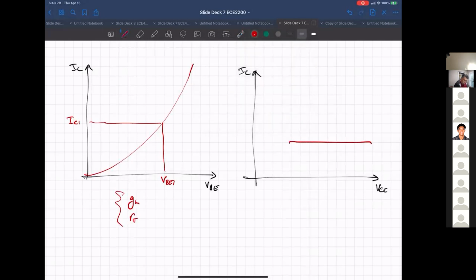you basically just want to calculate VCE to make sure you're not in this bad place. A lot of times when you design a circuit and it doesn't work the way you expect, you've screwed something up and VCE is too low and the device has entered saturation.